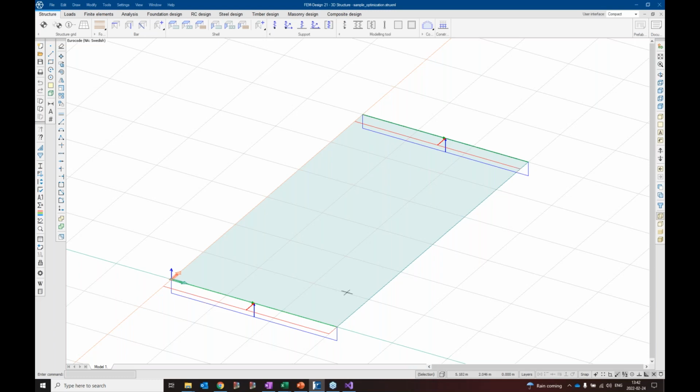Does that make sense? So I would expect if I have a very, very thin plate, then I will get loads of reinforcement, and reinforcement is quite expensive. So then I will probably get an expensive solution. But then again, if I have a very, very thick concrete plate, I will have so much mass that it will be expensive anyway. So the solution should be somewhere in between very, very thick and very, very thin, I think.